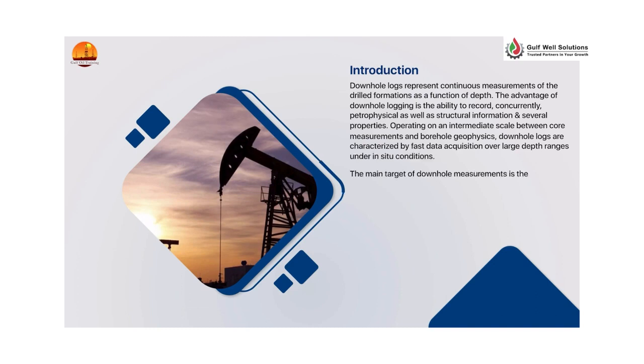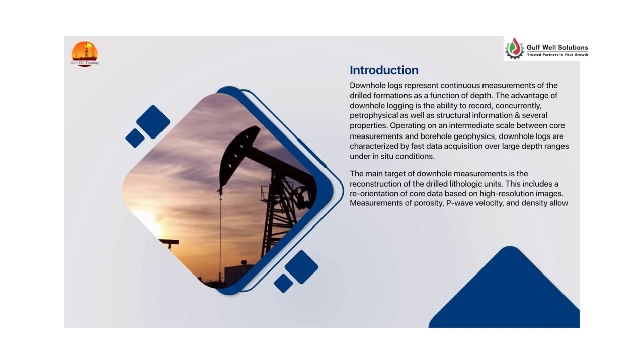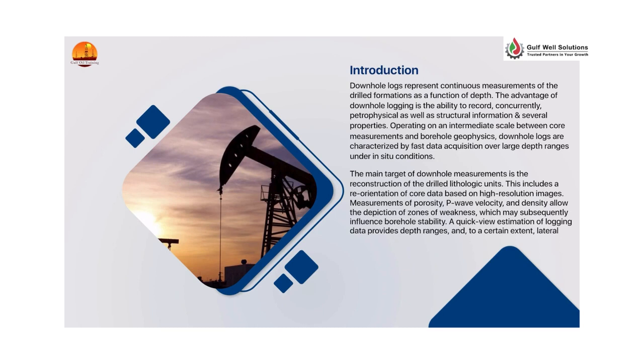The main target of downhole measurements is the reconstruction of the drilled lithologic units. This includes a reorientation of core data based on high-resolution images. Measurements of porosity, P-wave velocity, and density allow the depiction of zones of weakness, which may subsequently influence borehole stability. A quick view estimation of logging data provides depth ranges, and, to a certain extent, lateral extension of these zones.